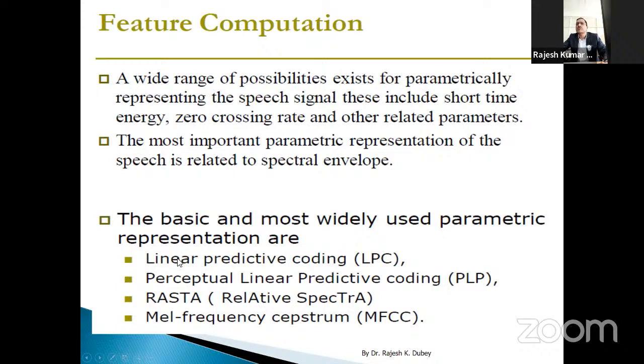The most widely used parametric representations, like LPC coding, are themselves a separate topic for a webinar. But after understanding the speech signal in the production part and in the perception part, we find different features. How to find the different features, we have seen in digital signal processing tools: perceptual linear predictive modeling, PLP modeling as we call it, and relative spectra. All these are tools of DSP. Then Mel frequency cepstral coefficients, where we talk about frequency converted onto the Mel scale, on a log scale, giving the Mel frequency cepstral coefficients.